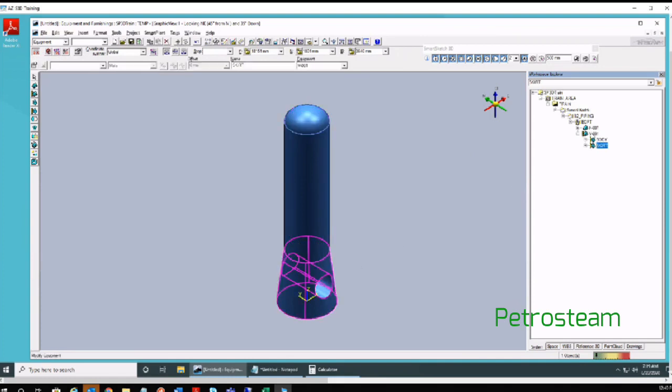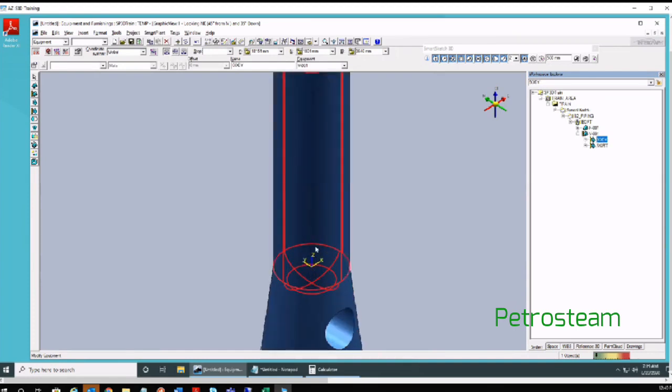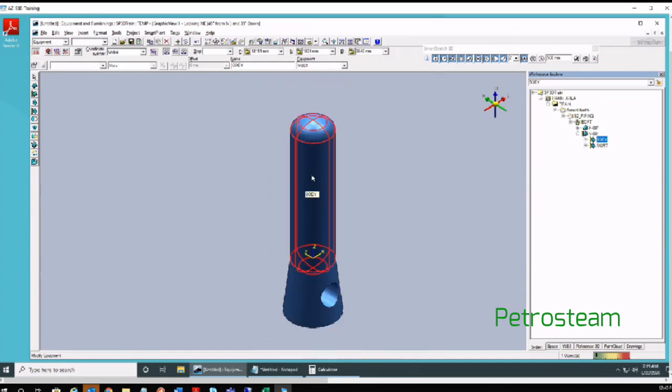Even though your equipment definition is here, if you want to rotate, move, or do any modification for the components together, it helps if you organize them. Right now, a cylinder and two dishes I placed properly with the cylinder. If by mistake they are at the wrong coordinate, moving them together will be easy if I organize them in an equipment component.